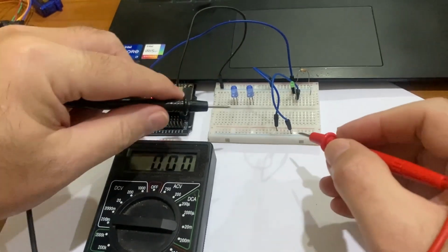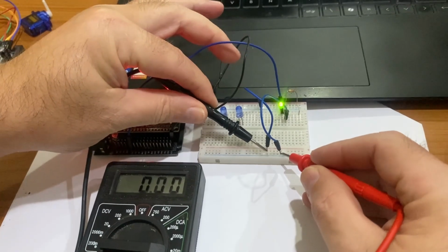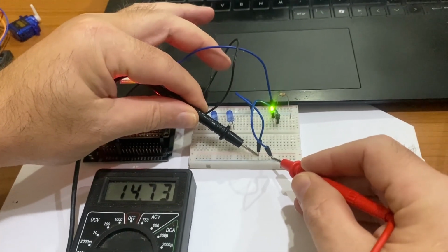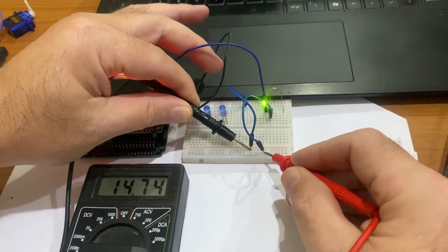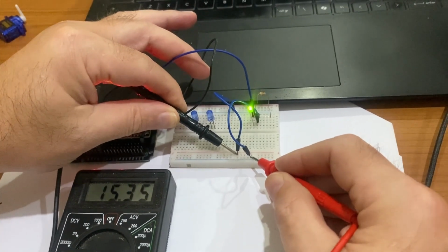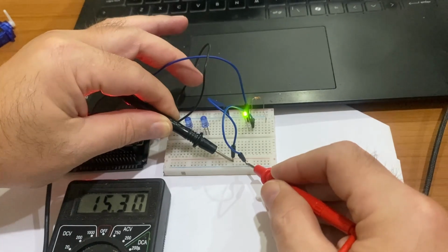I've now removed the resistor, which is not a good practice, and when I now put the meter across, you can see I'm getting nearly 15 milliamps. If this goes much above this, I will be seeing the magic blue smoke. Plus I'm also over voltage for the LED, which is possibly really meant to be around 2 volts for this size of LED. So this might go up in smoke as well at some point.